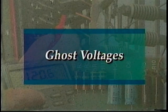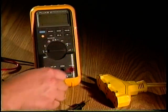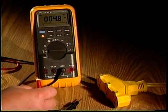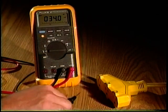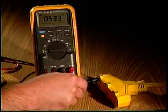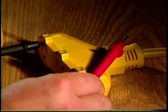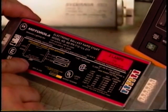Ghost voltages. A DMM set to measure voltage may display a reading or ghost voltage before the meter is connected to a powered circuit. Ghost voltage is voltage that is not connected to a powered circuit and appears as changing numbers on the display. Ghost voltages are produced by magnetic or electrostatic fields generated by current-carrying conductors, fluorescent lighting, and operating electrical equipment.